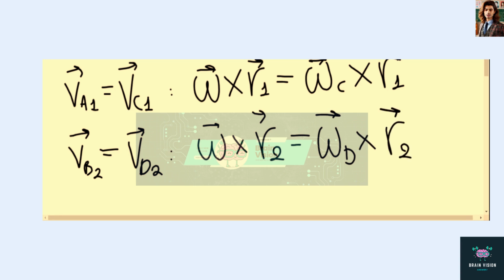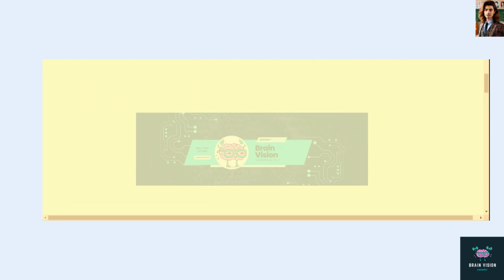Okay, we have to be careful here. The next step is to write down the position vectors R1 and R2 and do the calculations to see where they lead us. But we have to be careful because in order to use this formula, we need to take the positions for points 1 and 2 with respect to an origin which belongs to the lines of the axis of rotation for all the gears A, B, C, and D. So I hope it becomes obvious from the drawing that point F is the appropriate choice for our origin.